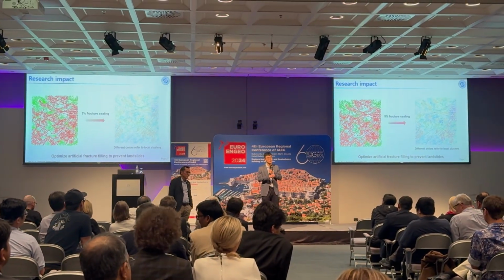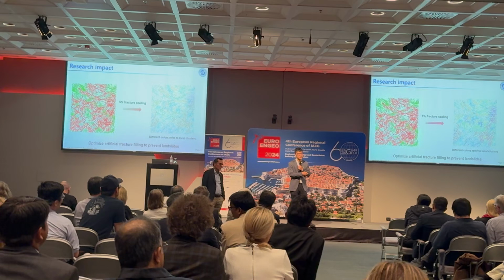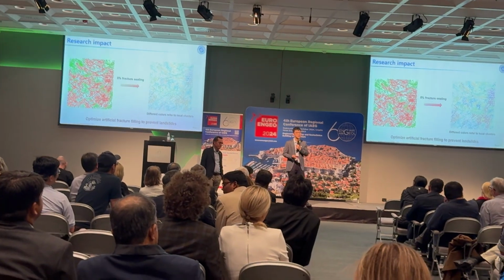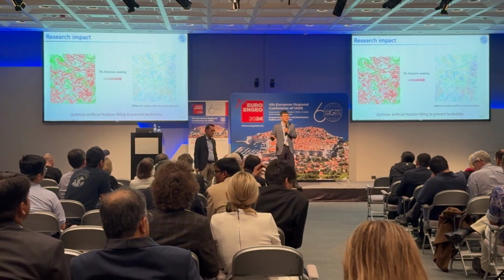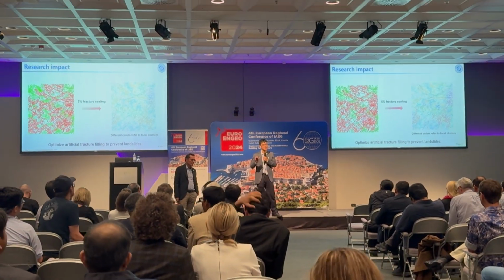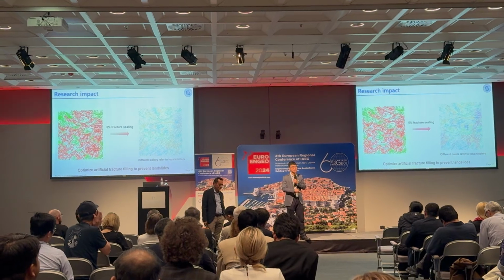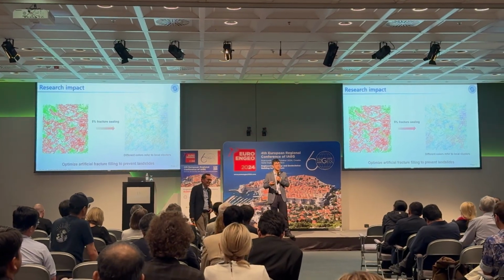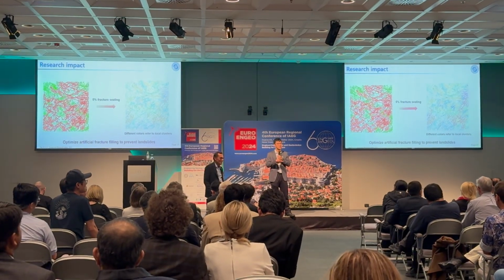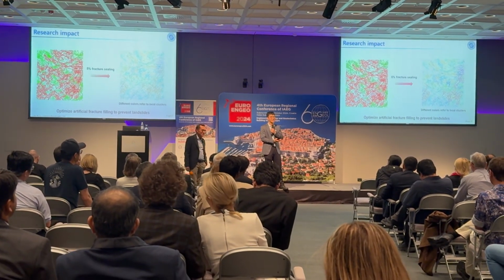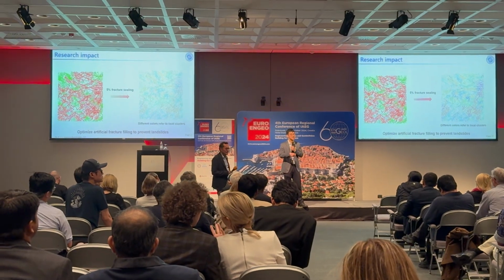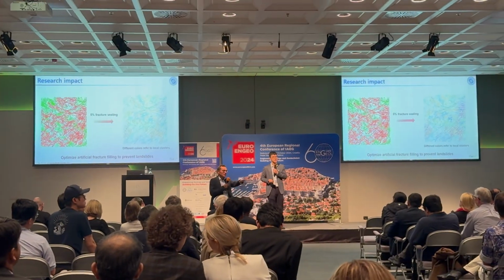That's why I do not extract aperture information from the fracture outcrop images, because it's not that trustworthy. After a very long geological time, with weathering and everything, I don't think the apertures nowadays can represent the apertures of the real fractures. So the fracture aperture will also be described by a distribution, not by the measurement from the polygon.